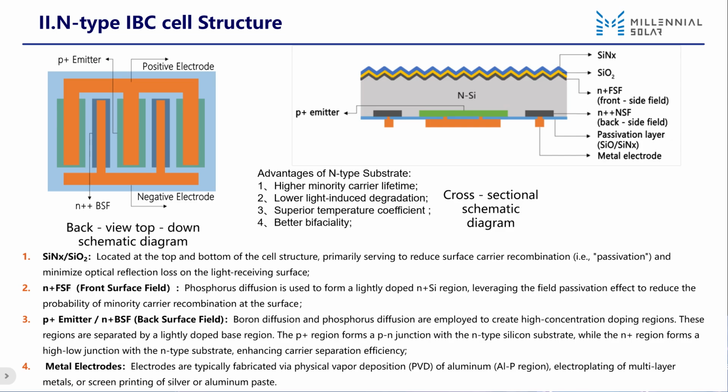Then there's doping in the bulk region and the back. What does heavy doping do? The N region is heavily doped with phosphorus. The more doping, the lower the resistance. So, we use heavy doping to reduce the resistance and mainly to minimize electrical losses. This is the P region emitter, as well as its back film and metal electrode.